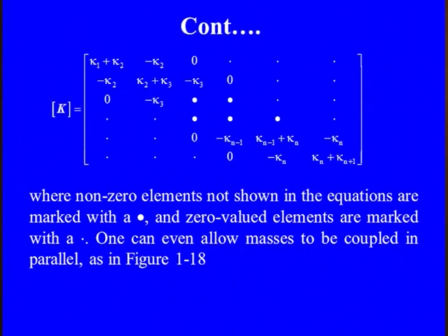And if you now go towards the stiffness part, it has a similar feature, because the deformation in the stiffness and the velocity in the damper are in a similar manner. No nonlinearity is there. Along with that, the elements in the matrices are also symmetric along the diagonal and they must be positive. So, with that we can see the stiffness matrix K1 plus K2, similarly K2 plus K3, and if you are moving towards the nth part, Kn plus Kn plus 1.